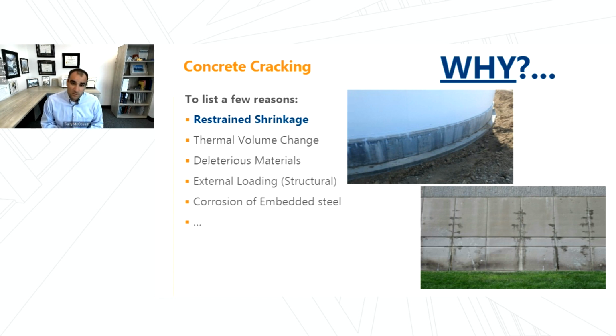Stephen also mentioned some deleterious reactions, such as ASR. Those are another somewhat common cause for cracking in these structures, given that they're exposed to a lot of moisture. But you've got to have a few things set up for that, in particular, having the material that is potentially deleterious located there. So that's one thing to consider in design for sure. And then you've also got structural loading, which I mentioned, and that can occur either just because it's exposed to something it wasn't anticipated to be exposed to, or perhaps design or construction left it a little weaker than it needed to be.